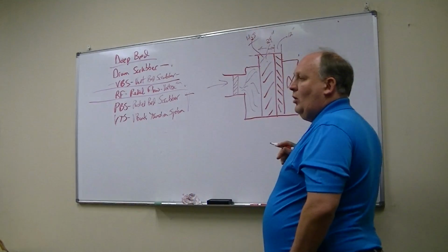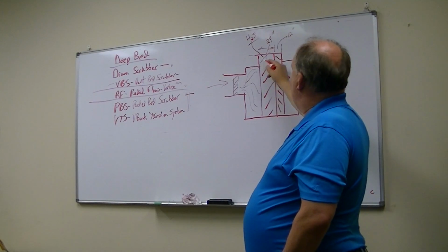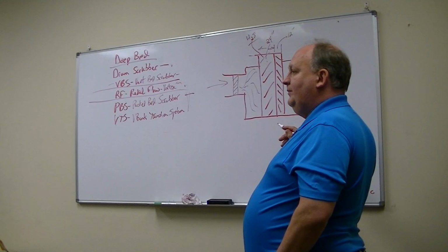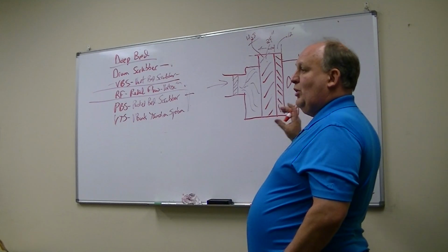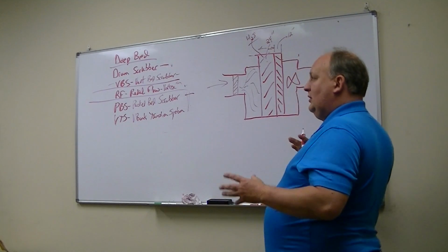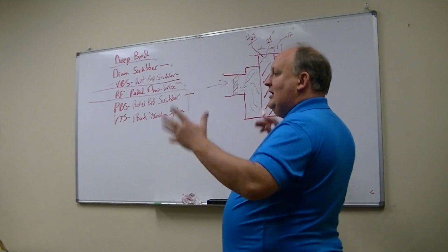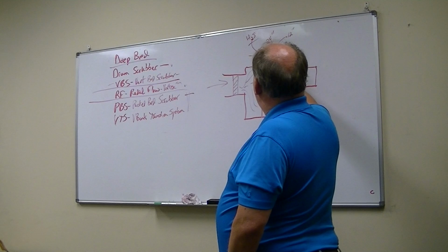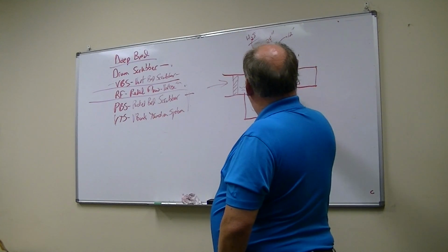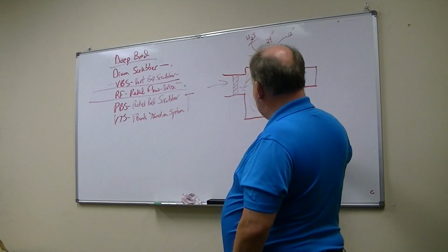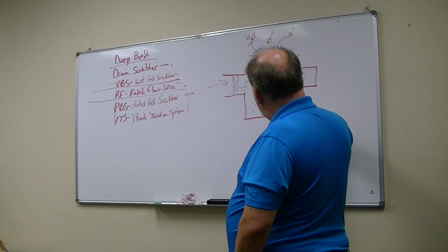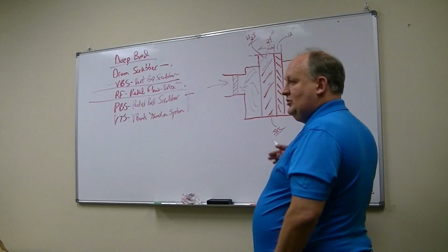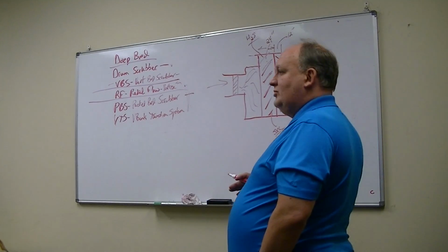So we're going to first use an adsorbent media which has a very high capacity for hydrogen sulfide, because that's the primary odor and has the most constituent. Usually 90% of the odor is one particular gas, hydrogen sulfide. So we're going to use one product to capture the hydrogen sulfide. We're not really talking about adsorbents right now, but I'll just mention it's usually Sulfazorb XL, which is fantastic for removing hydrogen sulfide.